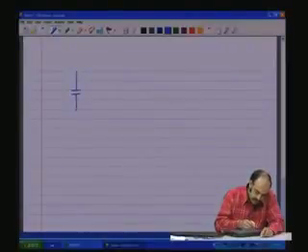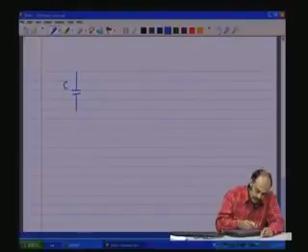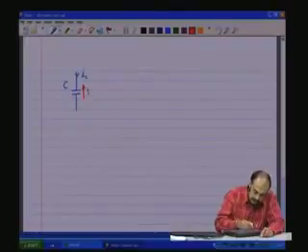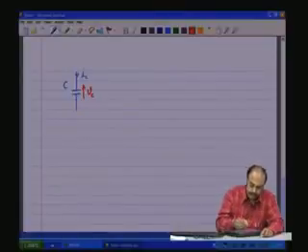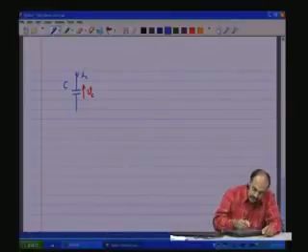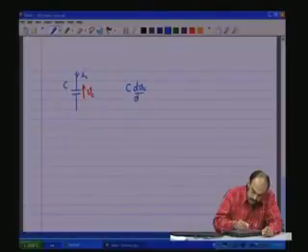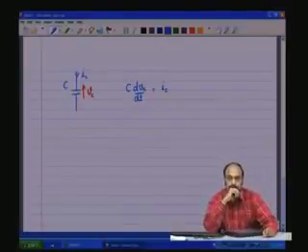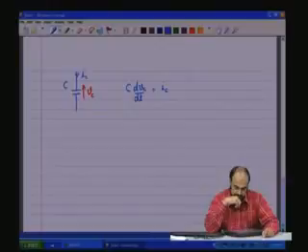So, we have the capacitance here C. There is a flow of current through the capacitance, let us say IC, which is going to result in a voltage across C, and that is Vc, with this positive and this is negative. So, for this dynamic element C, what is the equation? We have C dVc by dt is equal to IC. So, this is what we started with.